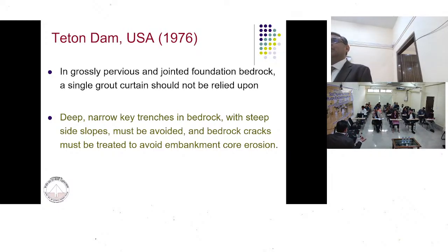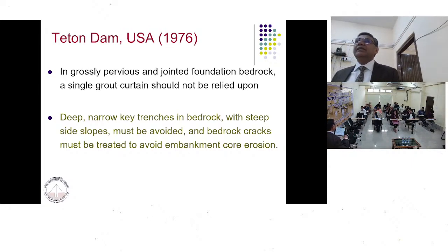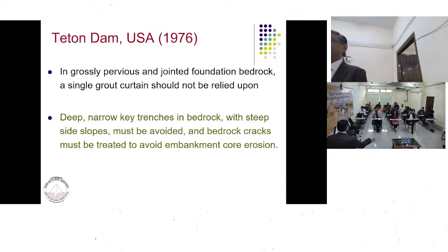So ultimately it was thought that the permeability had become very low, but grout intake was happening. The permeability test is showing that there is zero permeability, but grout intake is there. So then it was decided that ultimately it is the water meter that is faulty. And how did this occur? This occurred when some team visited there.